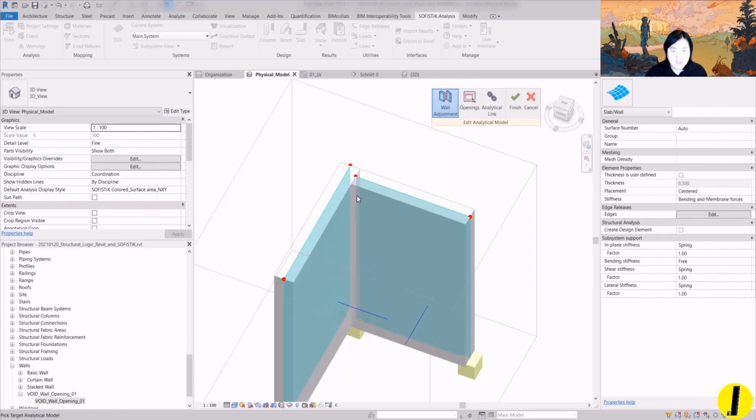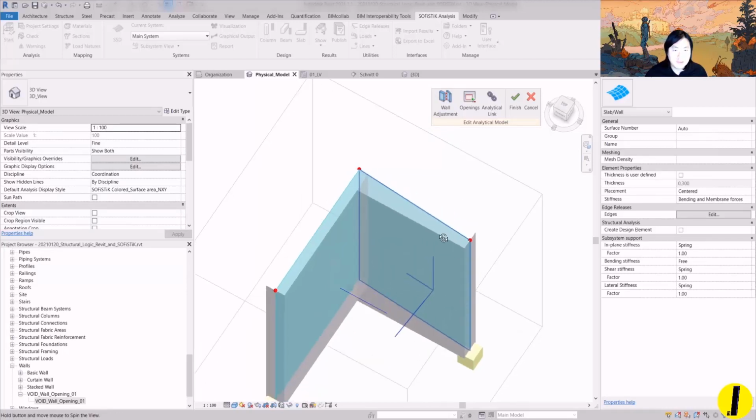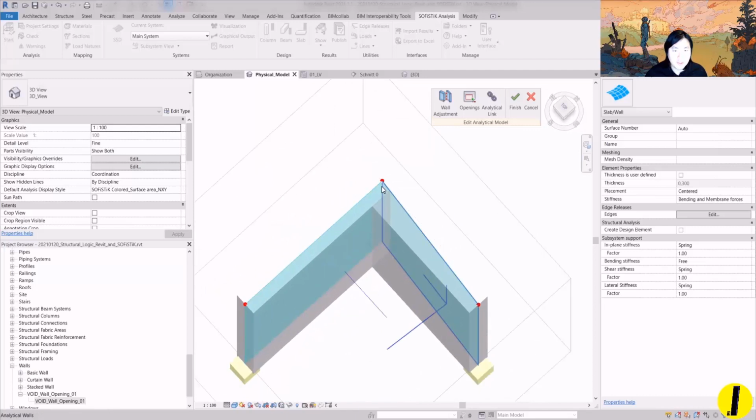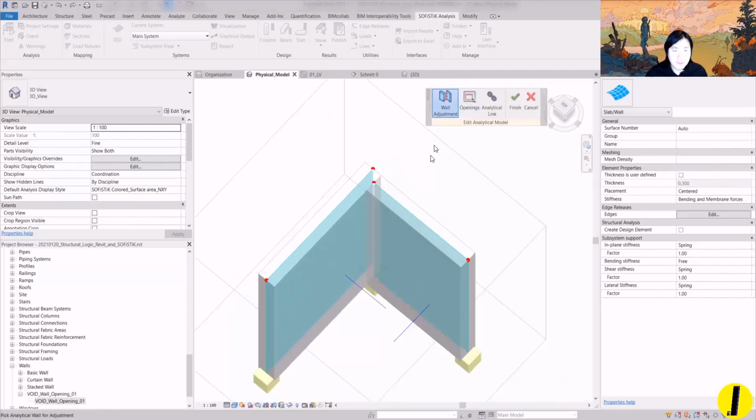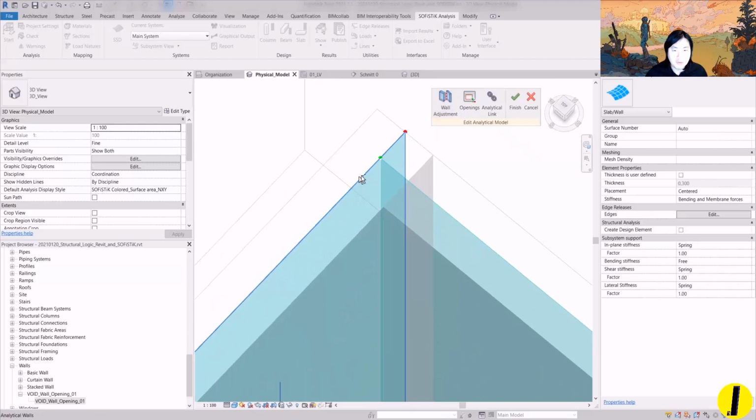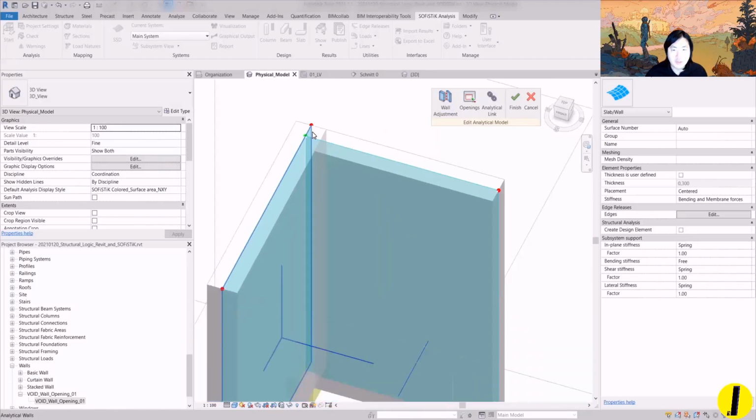I want to adjust this wall, and then it shows pick target analytical model. I want to target this analytical model here. In this case, it joined, but it's not perpendicularly joining there, which is bad. So I'm going to undo. Let me do this edge here on this horizontal boundary, then it just joined there, as you can see. And let me try again that one.